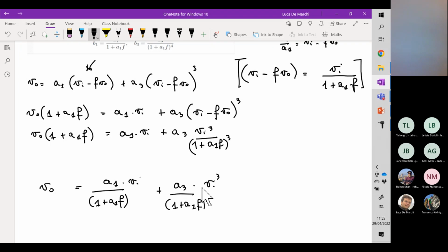Or, as you see, you can compute the phase margin as the distance of the phase curve with respect to the line at minus 180. So we have a quite consistent phase margin. 90 degrees means clear stability in the behavior of our circuit.